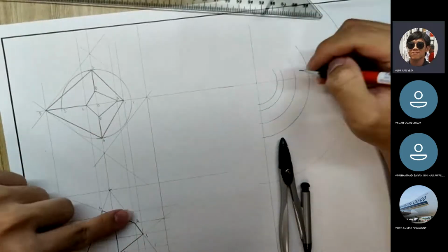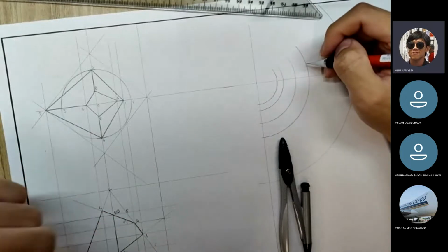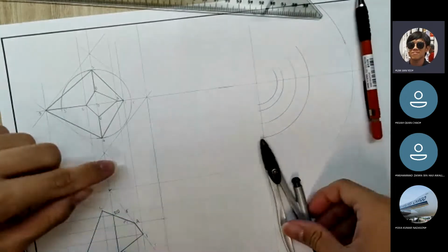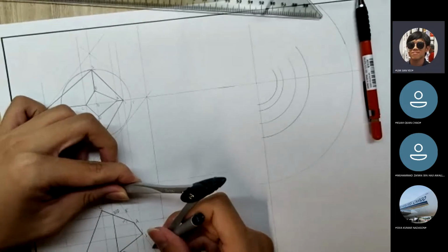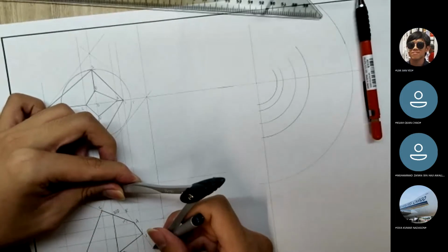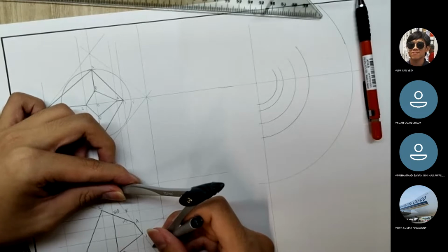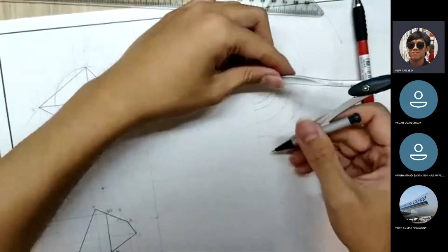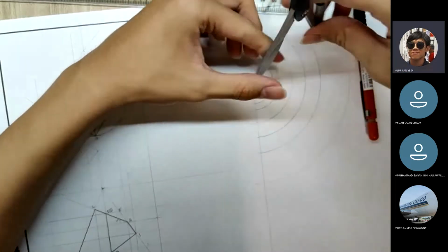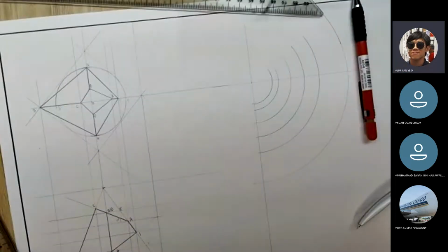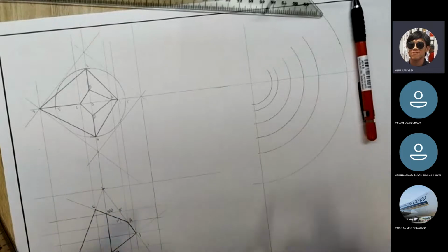This is the C line, this is the B line, the A line is the 1 line, and now for the 2 and 4 line, I do the same thing. Project the line horizontally to a true length. Then for the true length, you measure from the apex to the true length.